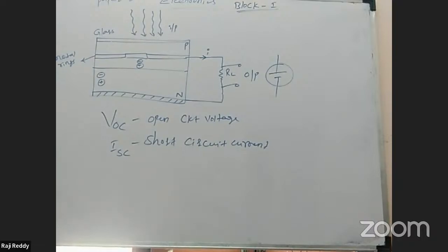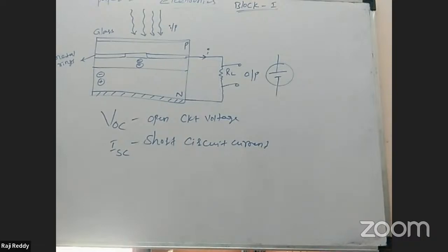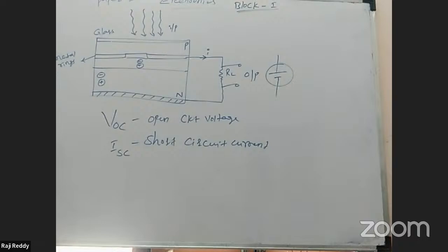About power consumption, 15 percent efficiency is obtained with a thin N region diffused layer into the P region. Solar panels providing 5 watts at 12 volts have been built to operate 24 hours a day by charging the batteries during daylight hours.